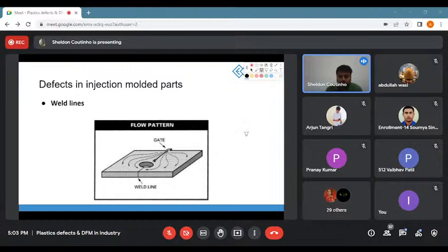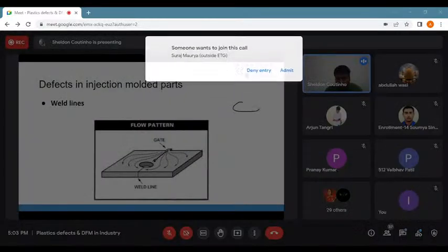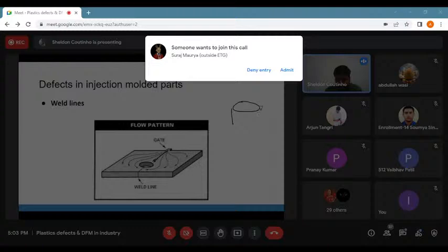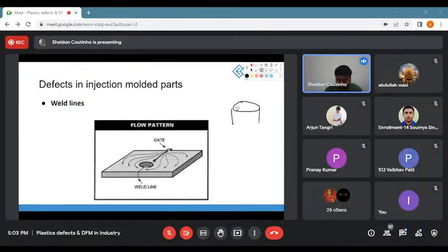Now, I had explained this with a cylinder. So imagine this is the hole. This is basically the cylinder that your plastic cannot enter and it has to go around it. So when your plastic comes from here as an entire jet, or a river kind of thing, now it has a dilemma. It cannot flow like this and then come around and meet over here.